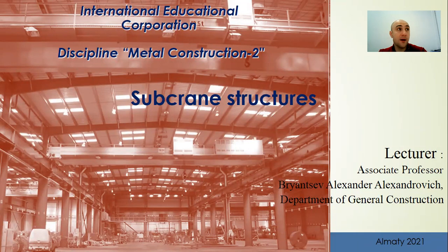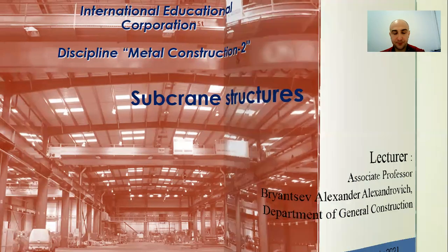Like steel crane girders, they also have T or I sections with the thickening of walls on the support. The dimensions of the beams are taken depending on the span between the columns, so pitch between the columns, and lifting capacity of the cranes.